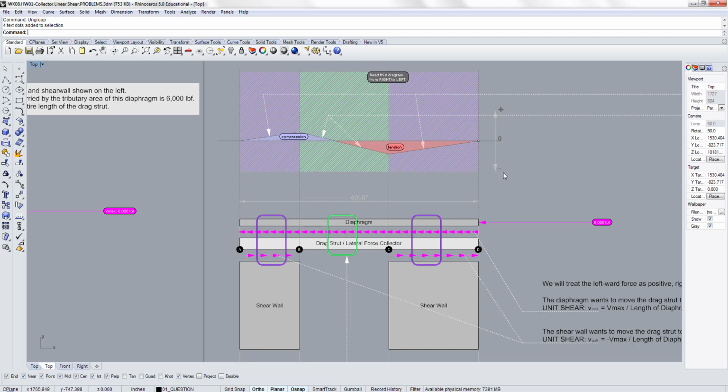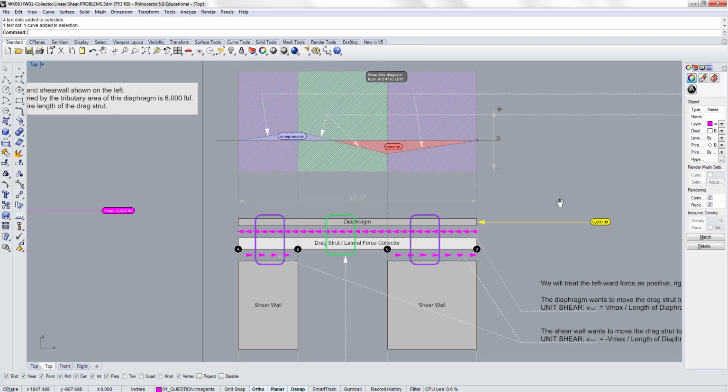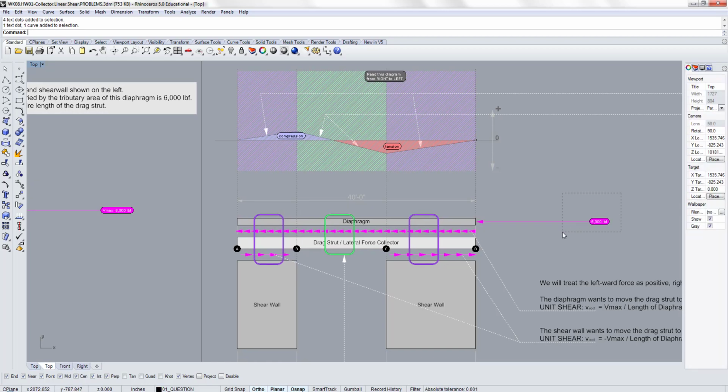Because this is a really abstract scenario where the lateral force is only hitting from one end, right? But an earthquake doesn't really choose direction. So you have to think of this scenario, but it can also be pushed from the other end. Also, an earthquake moves around. So I'm only looking at the shear wall in one direction, but the building moves around, so there have to be other shear walls going in the other direction on this building. But we're just looking at this wall. So we have to assume it can be pushed from this way or that way, right? So far it makes sense?